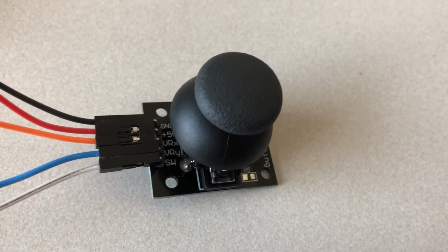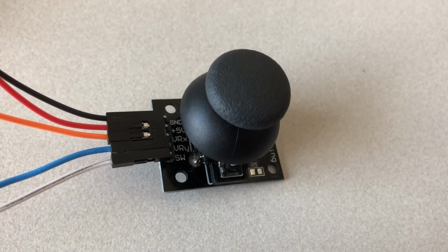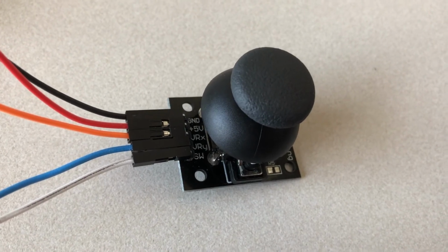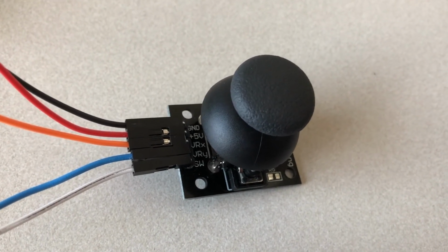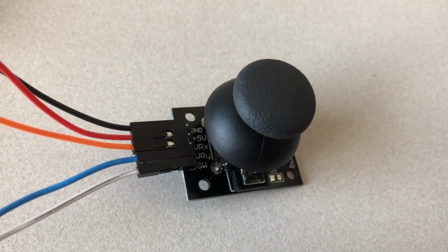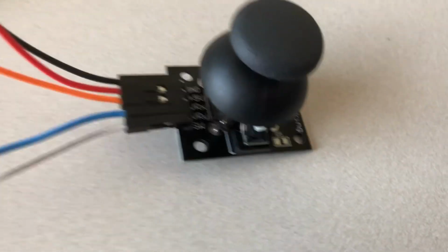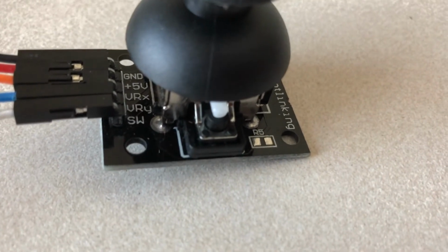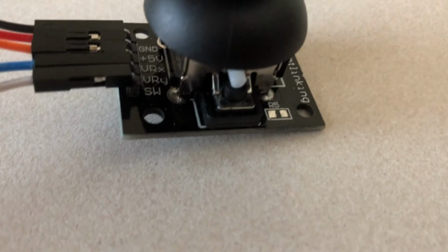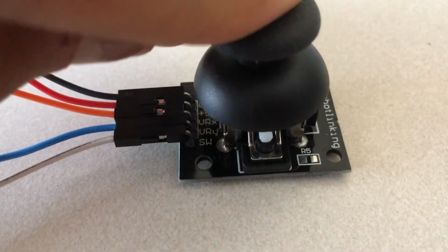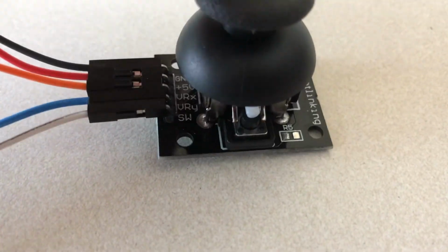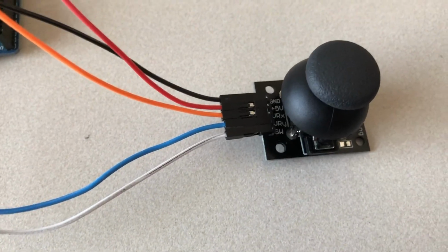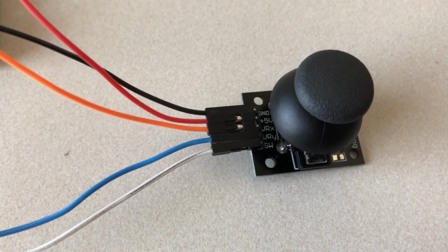So we'll start by looking at the joystick itself, and you'll notice that there are 5 wires connected into the pins. The pins are the ground, the 5 volt, the VRX, and the VRY, which are determining how far you've pulled the joystick in either direction, and the switch, which is pressing it in and out. And if you notice, the switch is literally just a switch right down there where you have the white little knob that when you push in on the joystick, it just activates the switch. Okay? So you can see how the different wires are attached, and now let's look at the Arduino board itself.